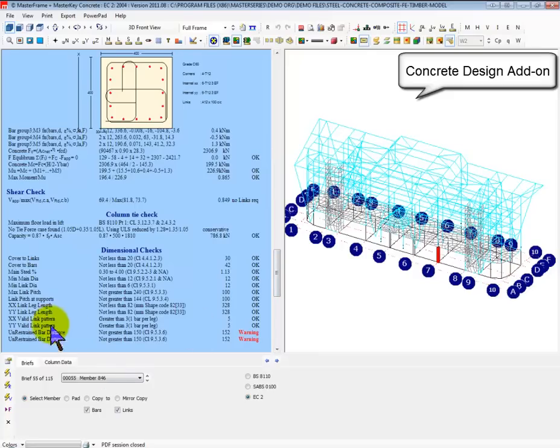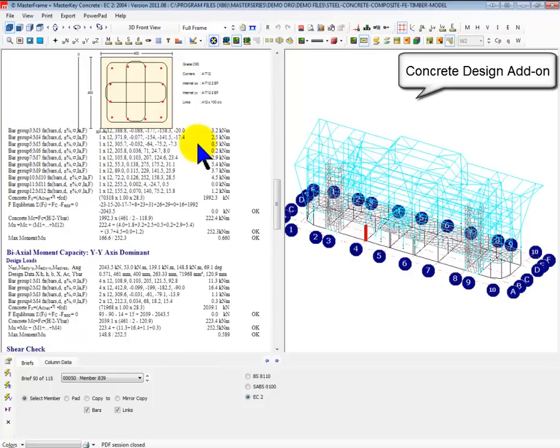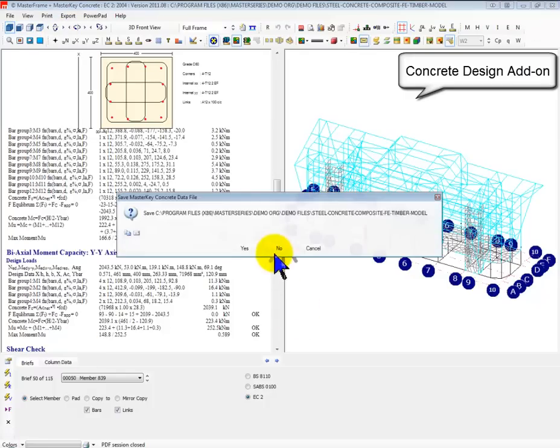It's just a curtailment problem. We probably need a bit more restraint distance. These distances are just too far apart. That can be worked on and sorted. This one, happy, it works. And that's your concrete design, from which you can then go through and do scheduling and things like that. I'm not going to do that. As I say, this is a frame analysis day.